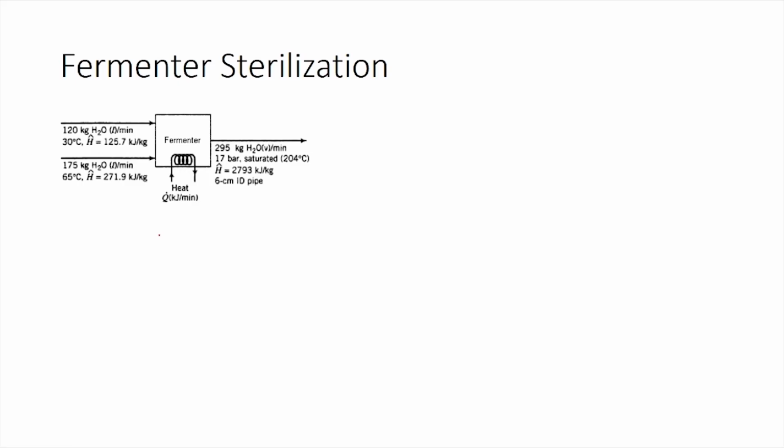How can we convert the mass flow rate that we have into volumetric flow rate? The steam tables give us information not just about internal energy and enthalpy, they also give us specific volume. Using specific volume, we can convert the mass flow rate into volumetric flow rate. So, let us first identify the specific volume for the exit stream.